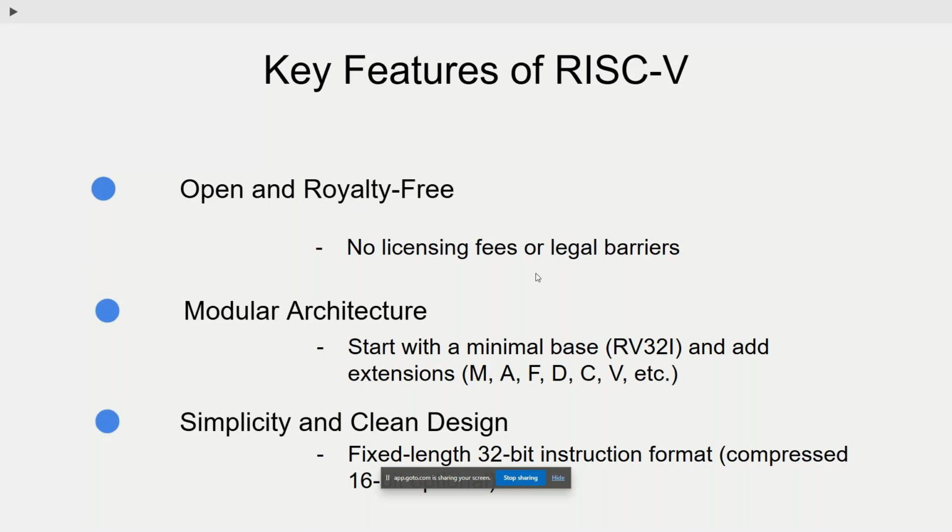If certain parts of the instruction set are not used and I'm still synthesizing them, what could be the possible issues? Basically optimization for area will be difficult, and maybe area and power will be an issue.